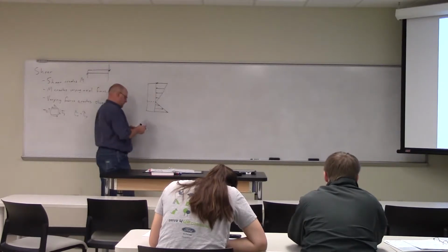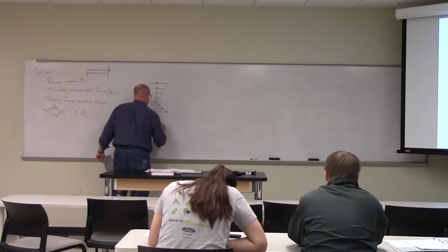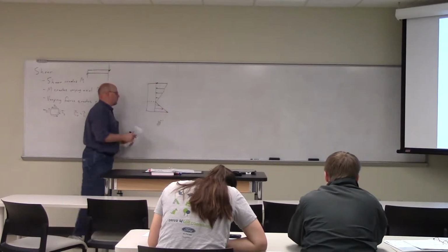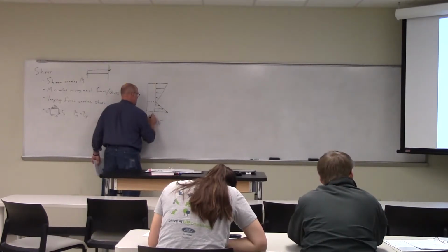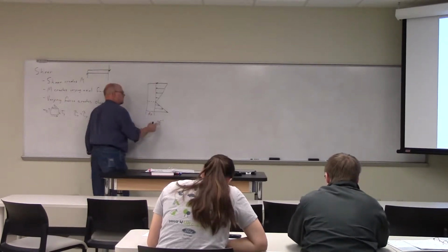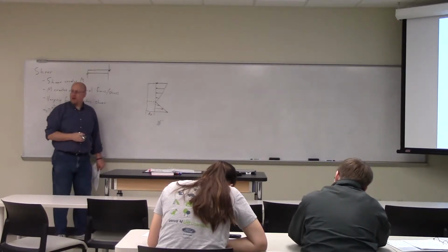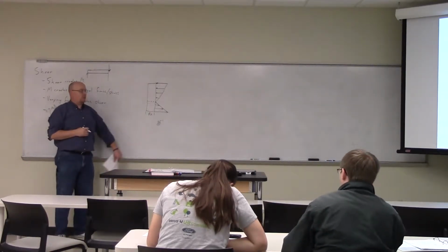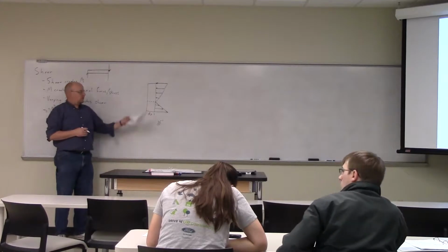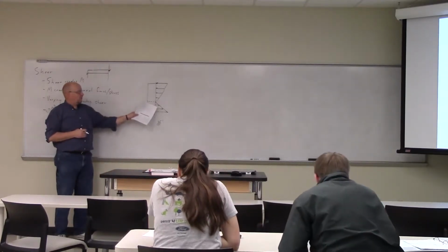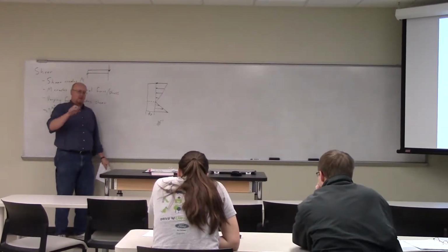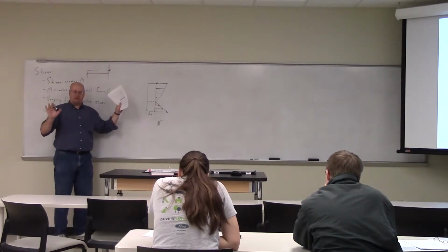So we'll call this whole force on this side dF prime, the total force for this little increment dx. So dF prime is the total force pushing back from the right-hand side. And dF prime is equal to 0, because the compressive stress is exactly canceled out by the tensile stress through the neutral axis. That's how we did that whole analysis for bending.